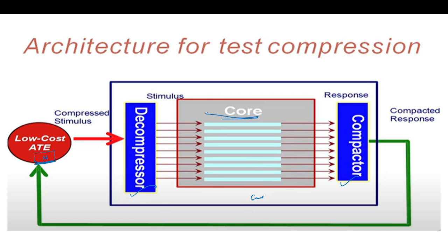So they will provide a set of test patterns. After obtaining all the test patterns for all the cores, the number of patterns will be very high. So as the number of cores increases, the vectors also increase. So this exponential test pattern, here we need to compress so that we can use this ATE machine.